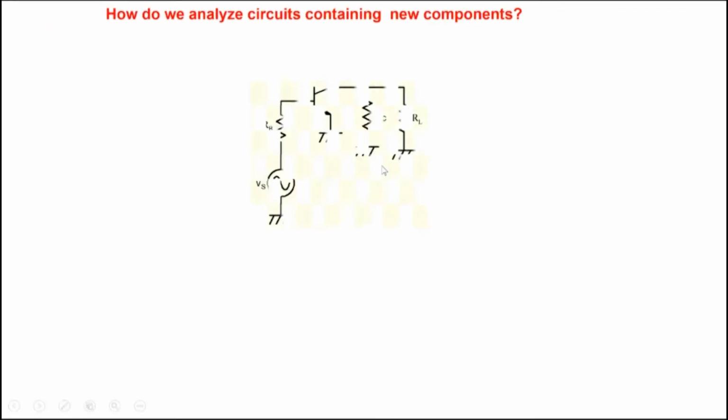Also, for example, let's say you would recognize that this is a transistor, and suppose I want to analyze a circuit consisting of this transistor, an R and an L and RB and all that here. Now, to analyze circuits, we have seen earlier, you apply KCL and KVL, but you need models. So for resistors, of course, we have Ohm's law. So we need a model for the transistor. Note that a transistor has 3 terminals here, one here, and one here.